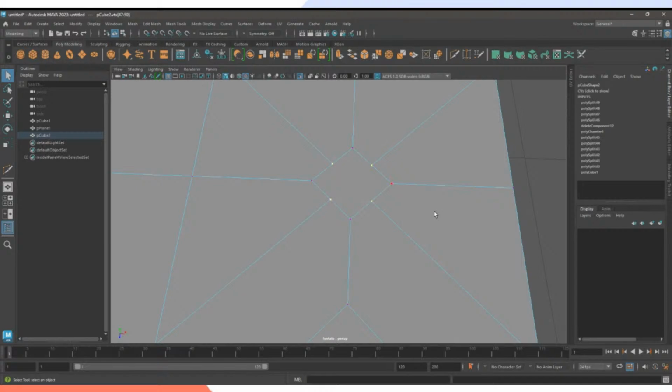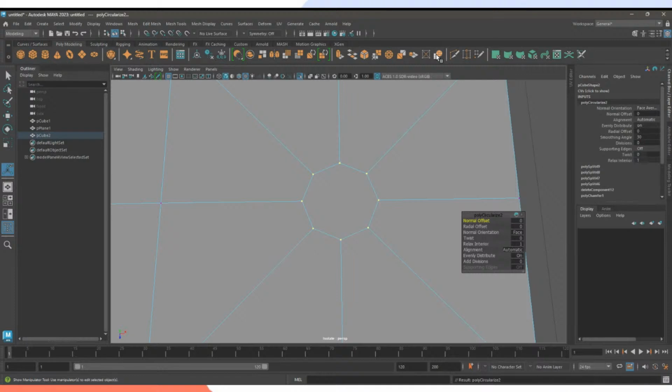One of the ways you can make a circle is either to do it manually by using the resize tool, the scale tool, and then boom, you have a circle. But sometimes it's not going to be a perfect circle. We want a perfect circle. So we're going to undo that. Select the rest of our vertices. Press Q to go back to selection tool so you don't mess around with your selection. And pick the circleize tool. This is a tool that you can use. You can either use manual or tools. Tools are cool. You can use them. Boom. A perfect circle.